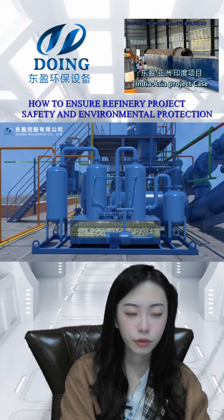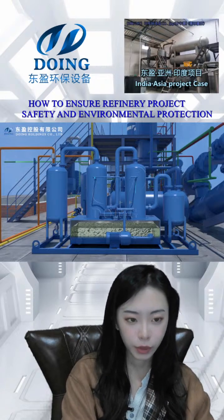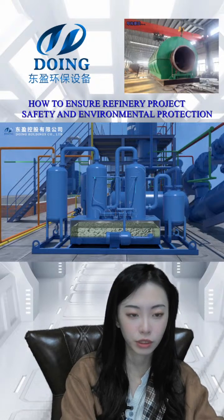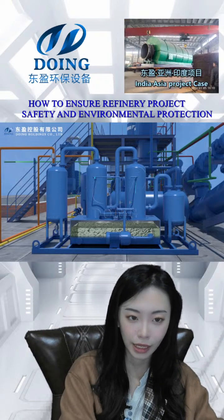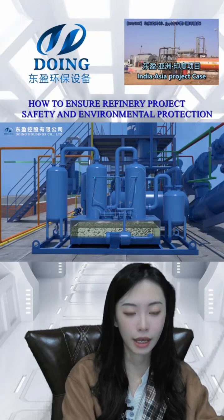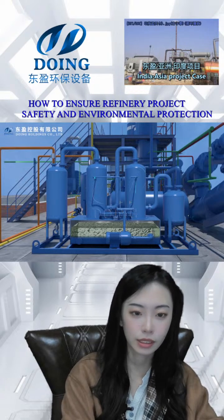If we burn the tail gas directly, it will produce bad smoke during production. So we need to remove the hydrogen sulfide and some sulfur dioxide inside to purify it. Then we can recycle this tail gas. We use the purified tail gas to generate electricity.